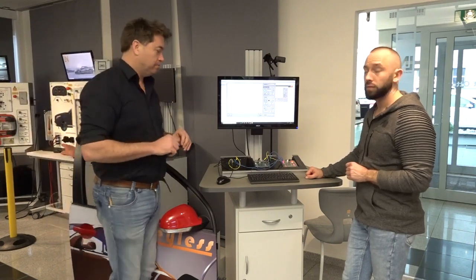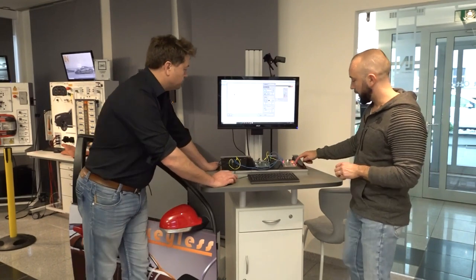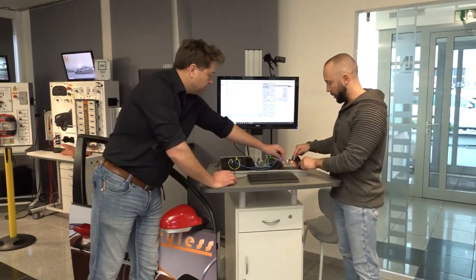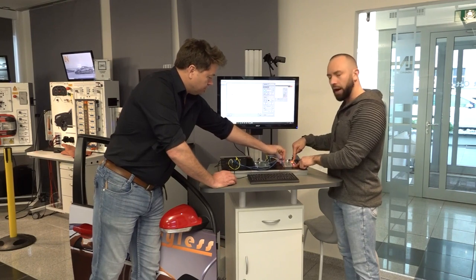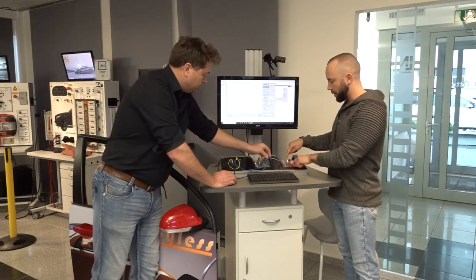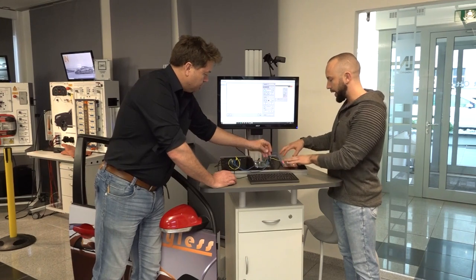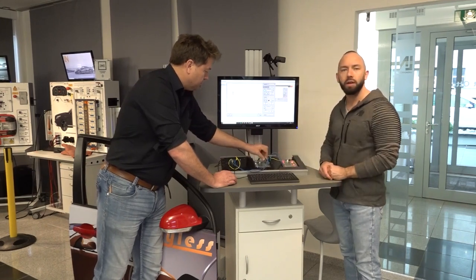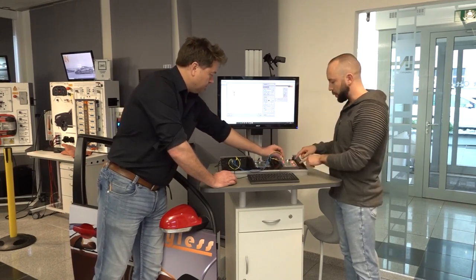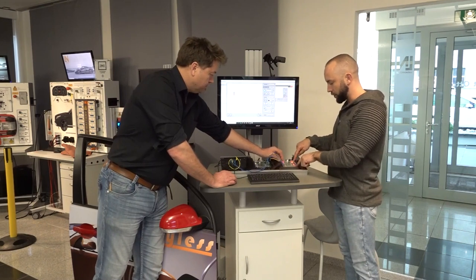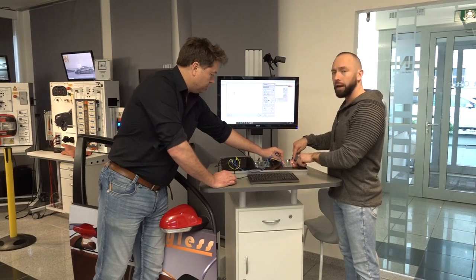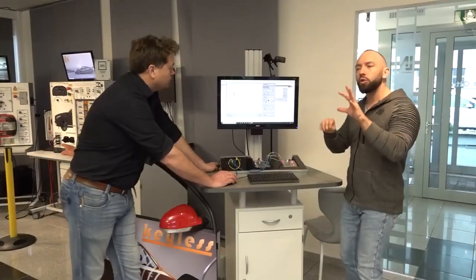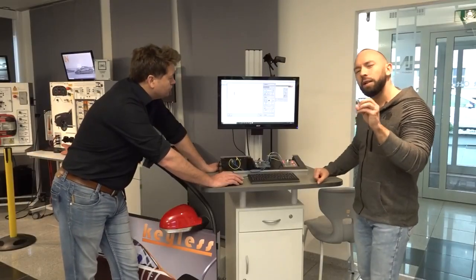And basically what you see here now, so that you do not wonder, is the principal behavior of the CAN high speed: the node which has lost one signal or both signals will stay in its last condition. Okay, that was why the blinking lights were just on. In a real car, that's a little bit different.